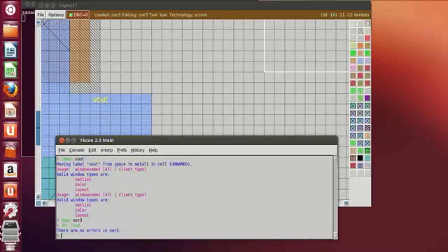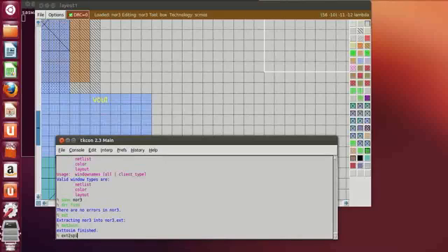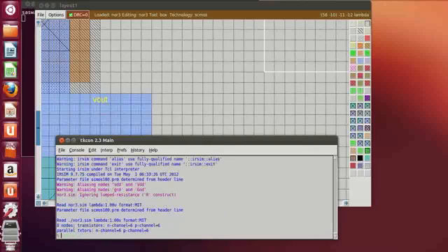Then find the DRC errors. No DRC errors. Then extract exe file generated. Extract to sim. If required, then extract to spice. So all the files generated. Now time to execute the sim file. So it's sim nor3.sim. Then watch W, VA, VB, VC, and V out.